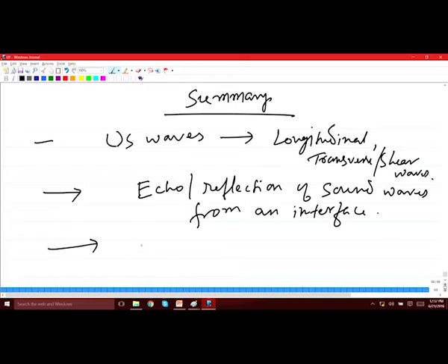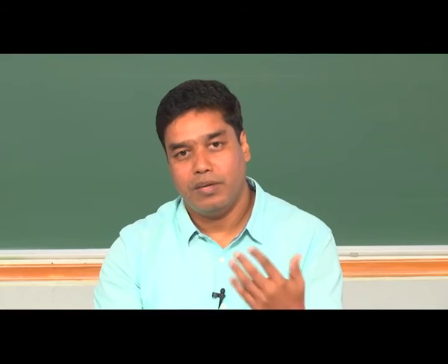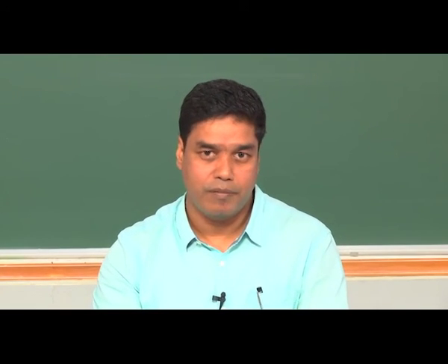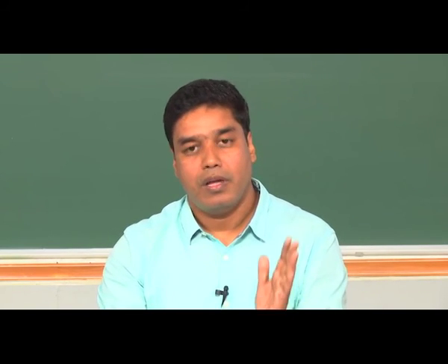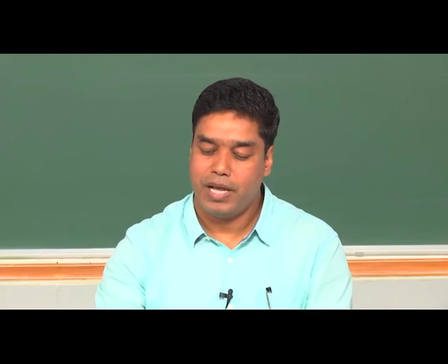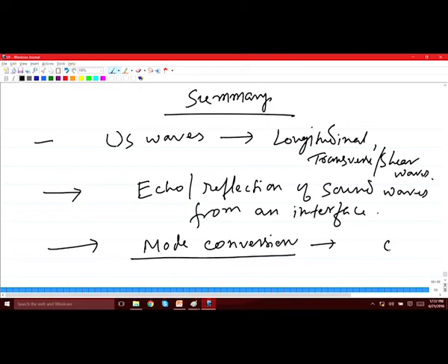Okay. So, then we talked about something called mode conversion. When you send the waves at an incident angle, a part of the longitudinal wave can convert into shear wave. And then I told you that if you want to do ultrasonic inspection by using angle beam, then it is better to exclude the longitudinal wave and keep the shear wave, and for that we saw that the incident angle has to be between the first critical angle and the second critical angle. And we derived this first critical and second critical angle based upon Snell's law.